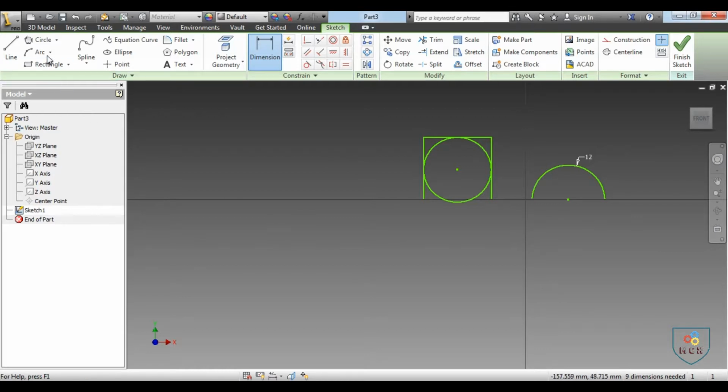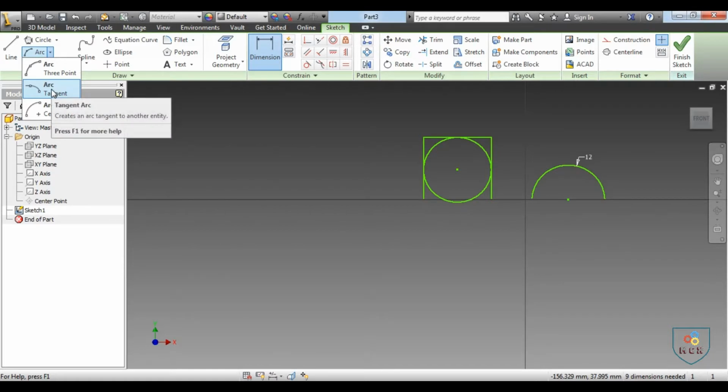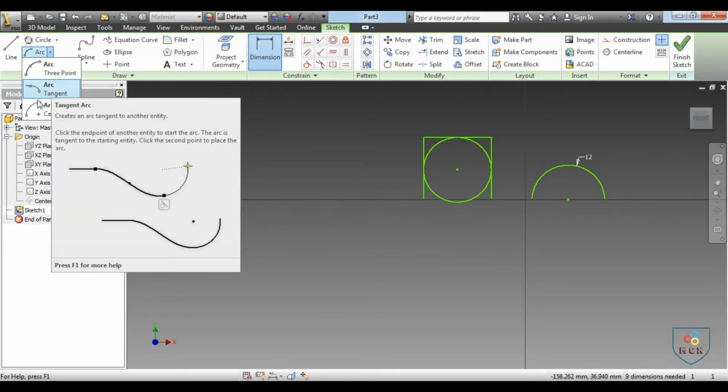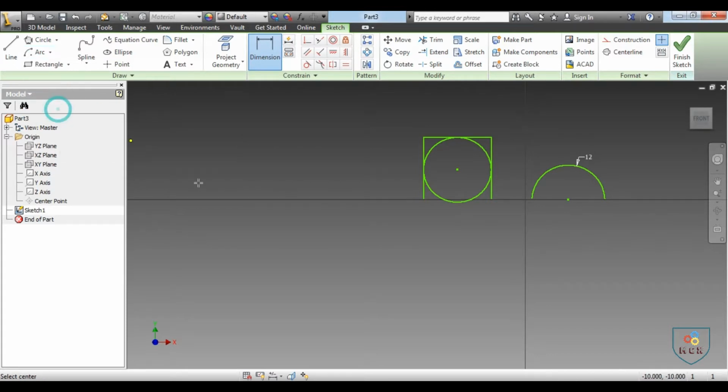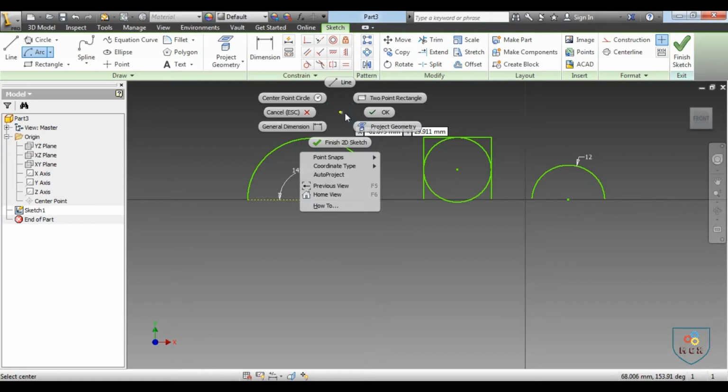So next we'll go for the R command. Again it is tangent. Similarly, if you draw the line, then it will be tangent over here. Next it is arc. For example, if you have a particular distance, then you can create the arc over here from first to last point, and how much is required depends on angles. For example, I require an arc of 145 degrees, which means this is the distance and this becomes the angle. Okay,